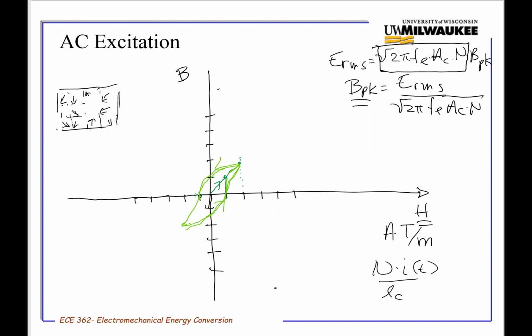So the current is going to increase, and it's going to follow a path that I'm showing, this green line here. As the current increases, it starts at 0 and goes up, and hence the magnetic field intensity in the core increases, and then it's going to hit what I'll call the H peak that's resulting from the current.